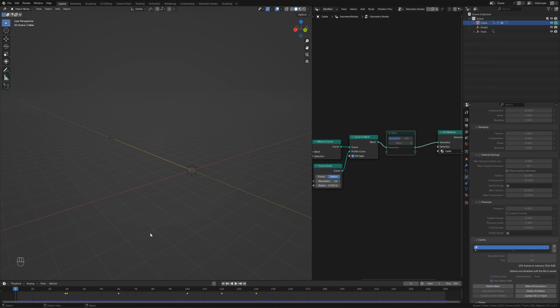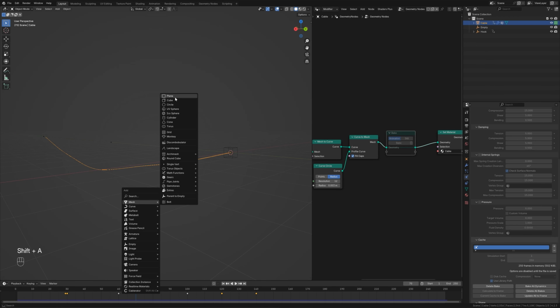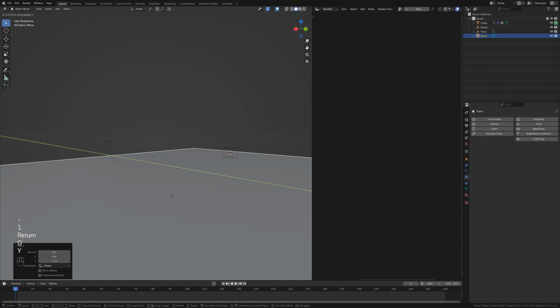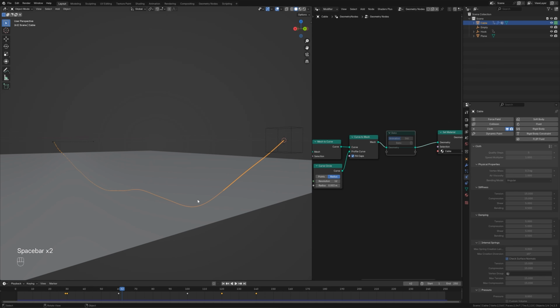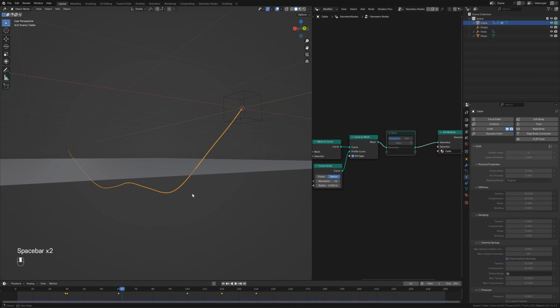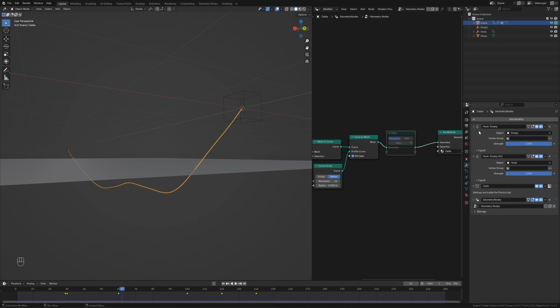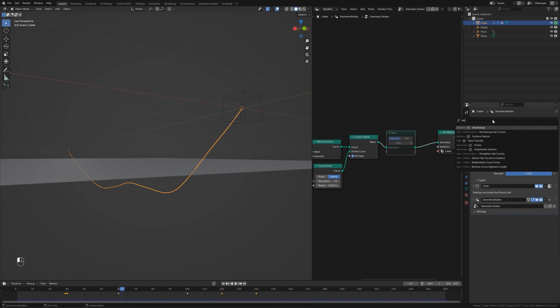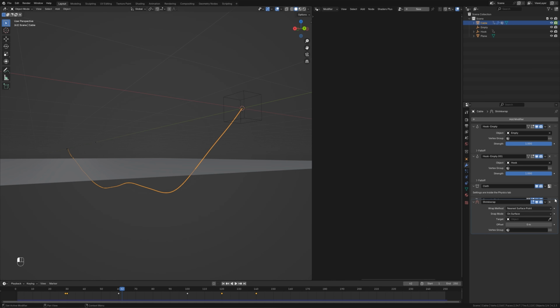To use this setup in a shot, you can parent the setup to a grapple gun prop using child of constraints and then just keyframe the value when launching the cable so you can animate the hook to a rigid point in the scene. One limitation with the cloth sim with only a line is that the cloth collisions don't work, but you can do a workaround with the shrink wrap modifier before the geometry nodes and set it to outside so the rope doesn't clip through the floor, for example.